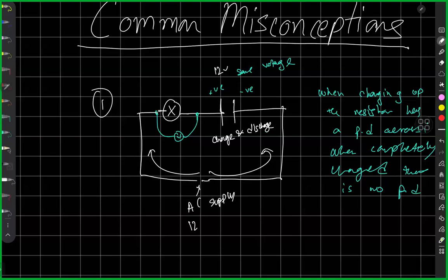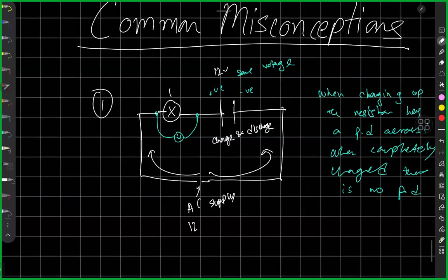So in such a case, the light glows constantly, even though there's a capacitor in series. Okay. Now, since the capacitor is in series and the bulb is also in series, and I have an AC supply, what really happens is electrons keep flowing through the circuit. Half a cycle in this direction, half a cycle in the other. So since current flow remains in the circuit, the bulb does continue glowing.